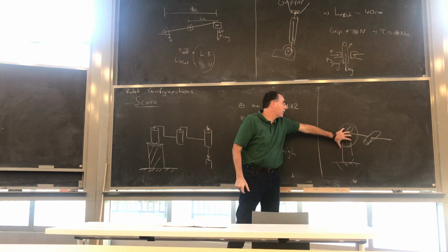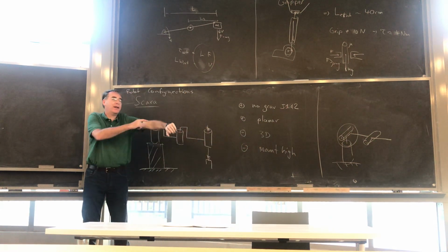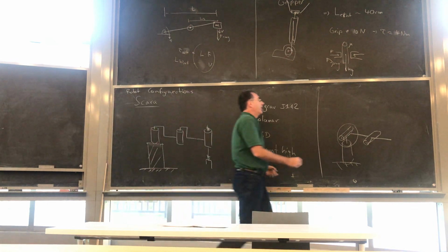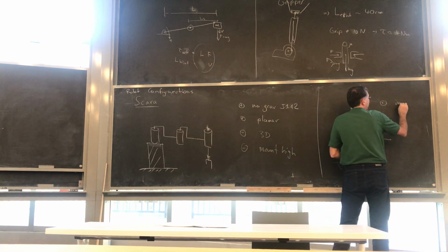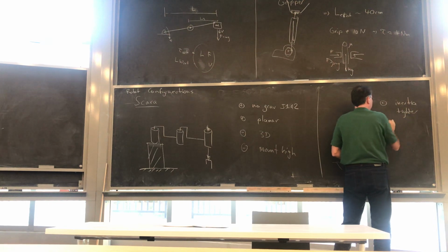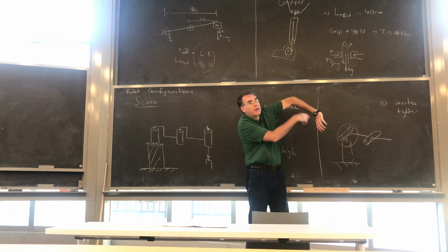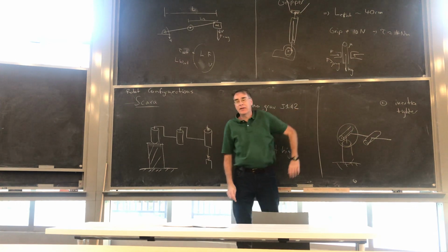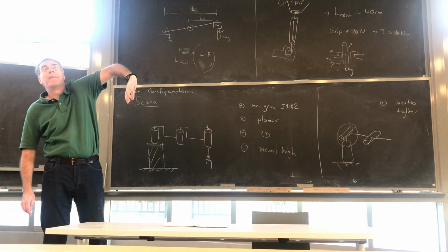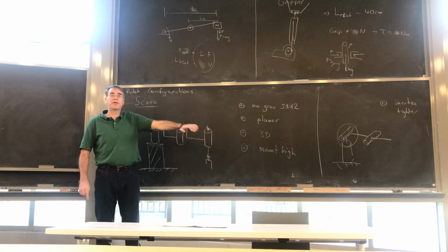Right? So you have a lot more mass pulled inside, whereas with this kind of robot, you actually have more mass sitting out farther away. So this actually is good in that the inertia is tighter, if that makes sense. And the big thing this is good at is reaching over stuff, because by definition, you get this arc. And so if we're bolting stuff to the table, that's actually a big pro. So I just wanted to go through that comparison. Those are the basic two configurations that people do.